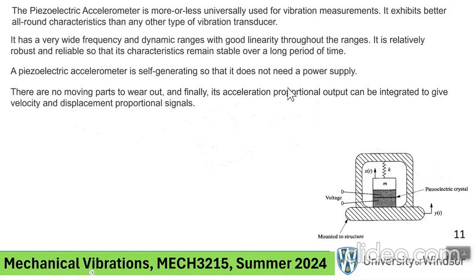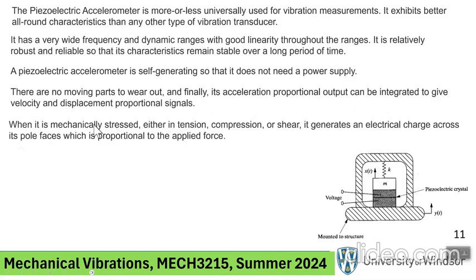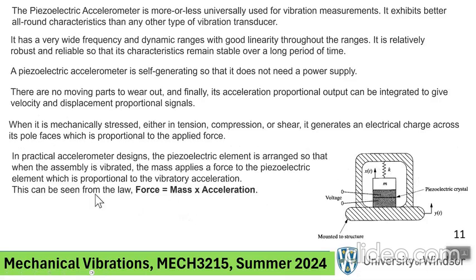So when you squish this thing, either in tension or compression, it generates a voltage. Now, generally speaking, piezo ceramics must be in compression. So even if you have a situation like that, you pre-stress it through a stud mounting so that it's always in compression. So if it ever goes into tension, there's already a pre-compression in it, so it doesn't completely become free.